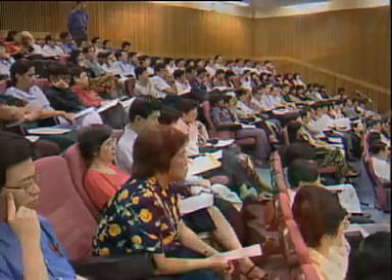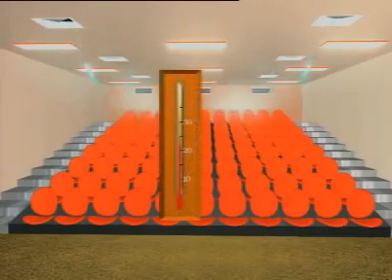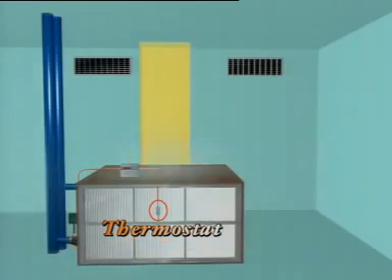To maintain the room temperature when the heat gain varies, the supply air temperature of the system has to be varied. In this case, the room temperature drops. A thermostat located at the return air path senses the temperature change.